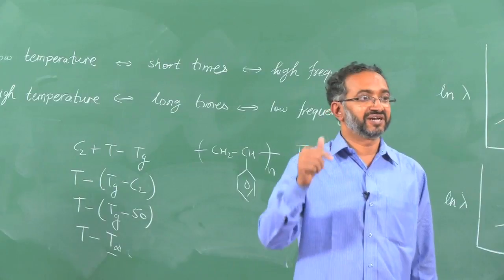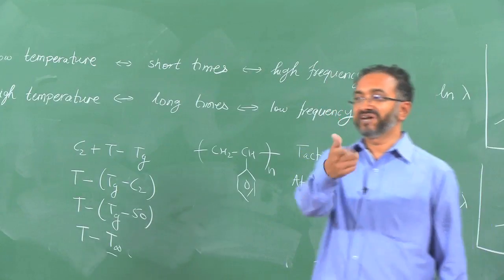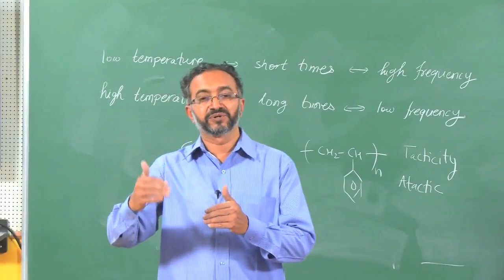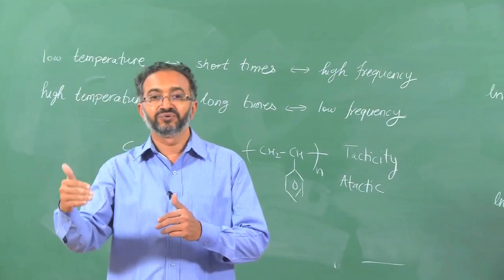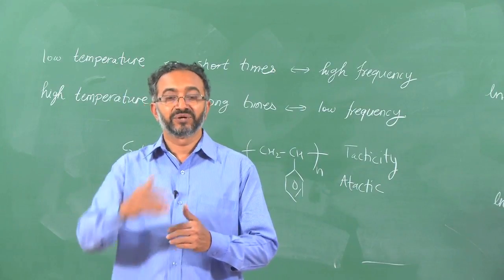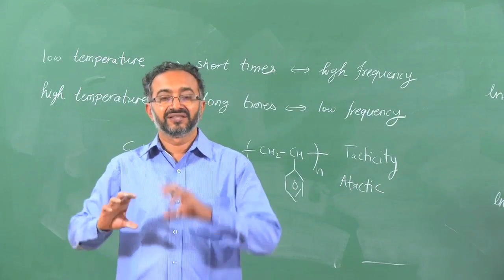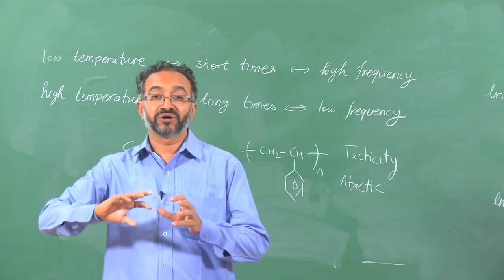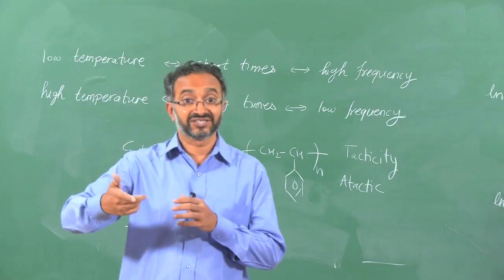So, some degradation reactions may happen. So, what you will see is, when you do time temperature superposition of 300 and 290, you will see that the 300 data is not superimposing well, because of the degradation reactions: the polymer chain length is changing, molecular weight is changing, and because of that the way entanglement works has changed.